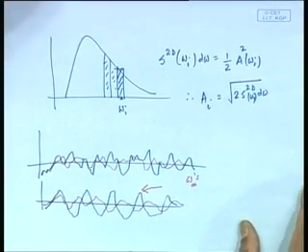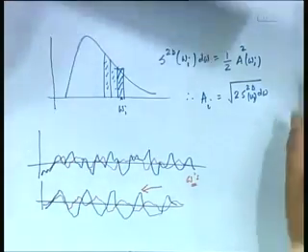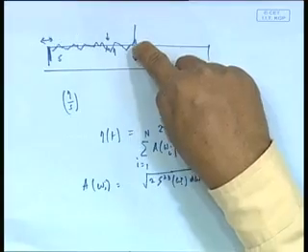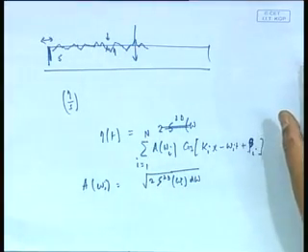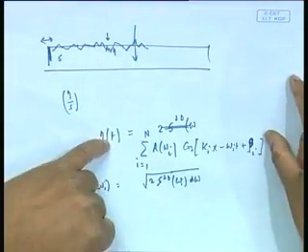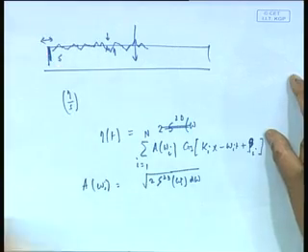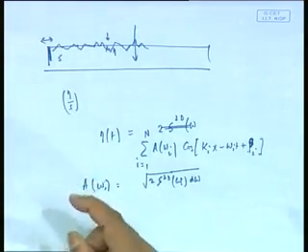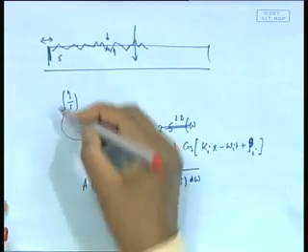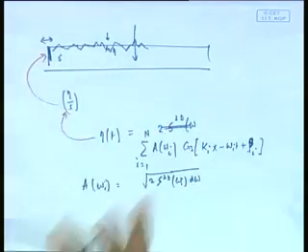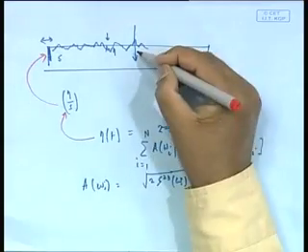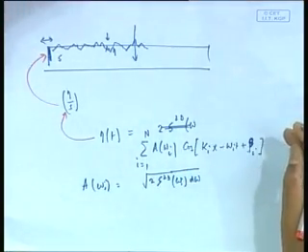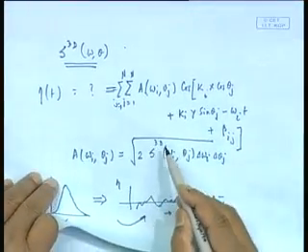The question therefore, you see here, that when I talk about experiment, now I have this interesting point. I have this tank, I have to create this wave. So, what we do, we break it down to this signal, then I break it down to the feed I have to give to this wave maker, and I give that. In order to get this, I have to find out what is the corresponding S value, and that I give to here, I push it that way. So, now see, if I want to make a 2D spectrum, I simply give this signal. If I want to give a 3D spectrum, I will give this signal.